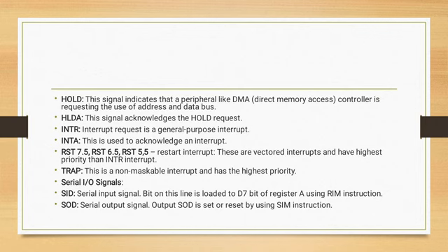Next, in this slide, we have seen that several kinds of pins are also available. One is called HOLD. This is an input pin. It indicates that another device is requesting the use of the address and data bus. Whenever there is a hold request, the microprocessor relinquishes the use of the buses as soon as the current machine cycle is completed. Then the processor regains the bus after the removal of the hold signal.